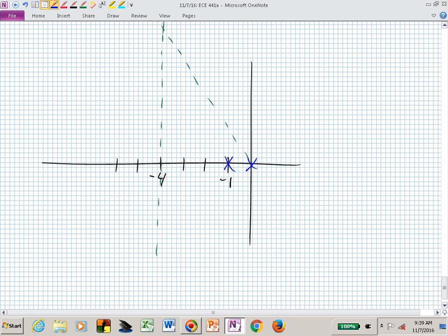Did everyone follow that? That's exactly what we need to do. So let me try to rephrase, not change the wording at all, but just try to restate what was said because you maybe didn't hear it. The easy thing would be to cancel. Let me do our controller in red. Let's cancel that pole, the open loop pole, and now the point was put a pole somewhere to the left to allow our root locus poles to eventually get to the left or at -4.